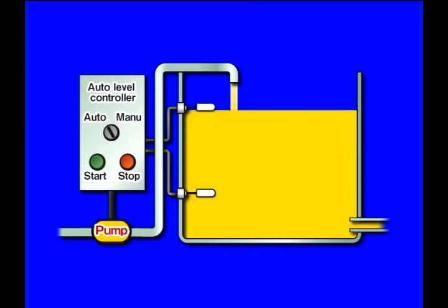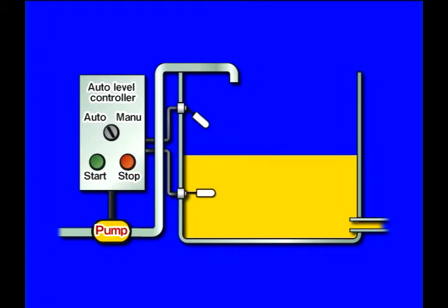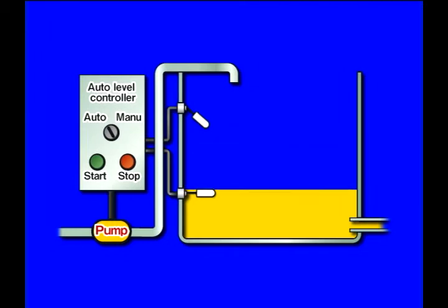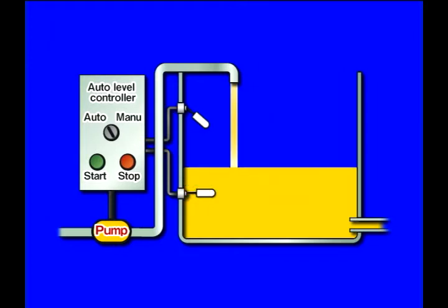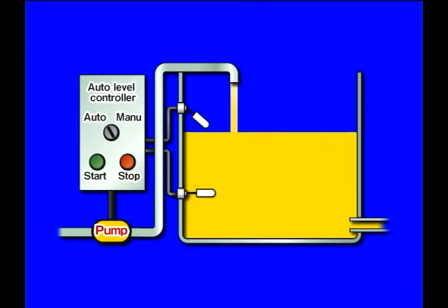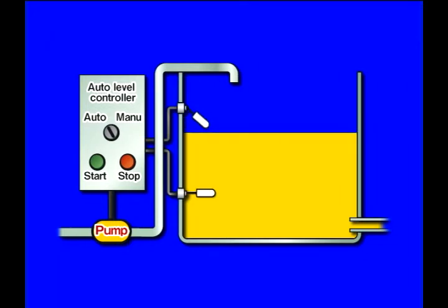Reduced insulation resistance between the coil, motor, and the motor frame can also lead to electrical leakage. To prevent such accidents, an electric space heater can be installed in the motor. The space heater is off when the motor is running, and it turns on after the motor has been idle for a preset period of time.